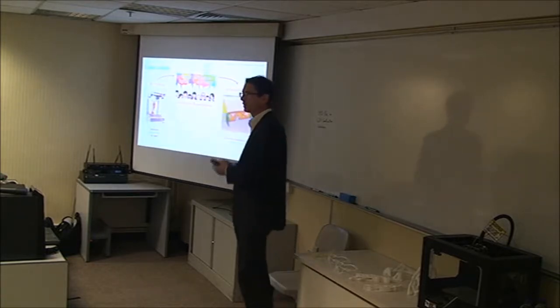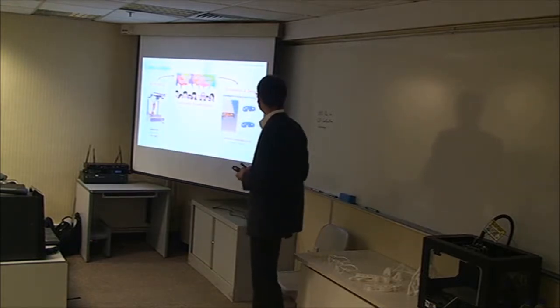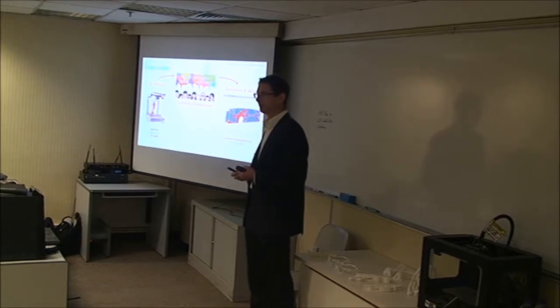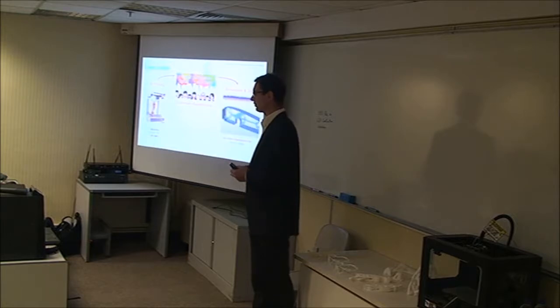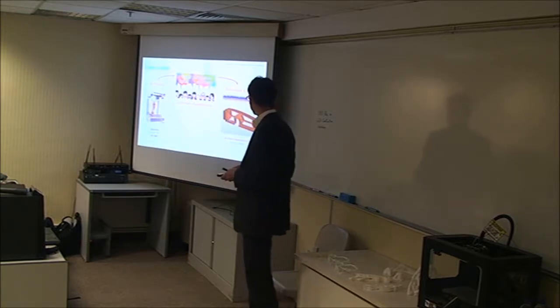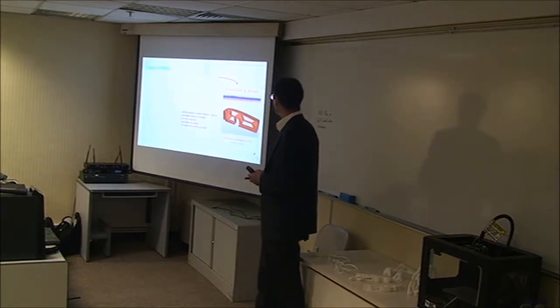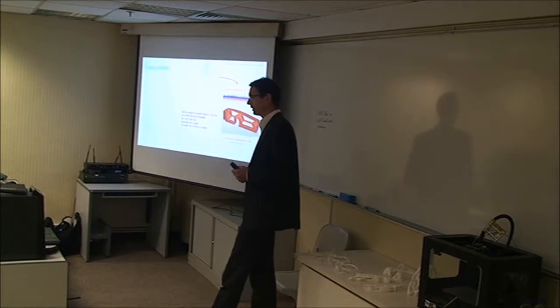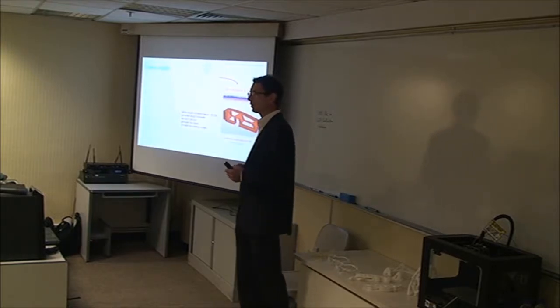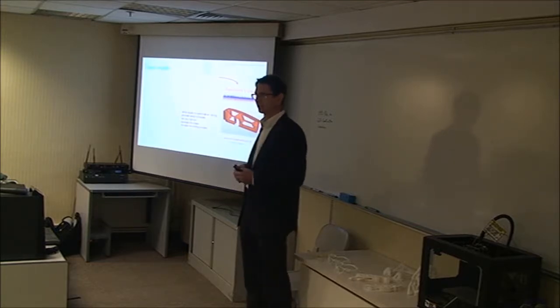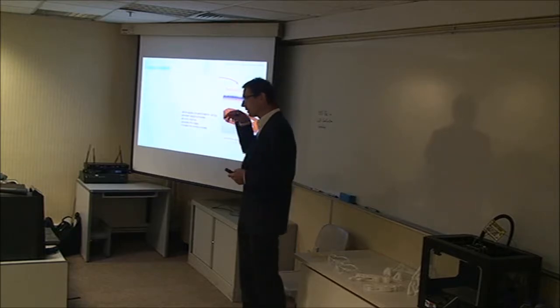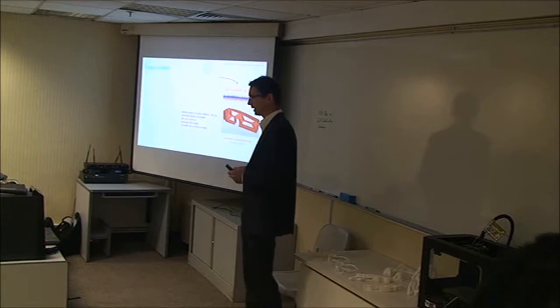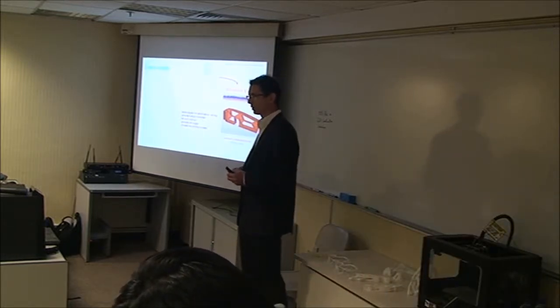So you look into the parts themselves. You look at how they perform. You find out the stresses, the load cycles they can stand for durability, for example, and that's where simulation is used. But therefore you have to define the target first, and that is very important when you do simulation and optimization, that you define exactly what you want to achieve. So what mechanical behavior characteristic you want to achieve, because when you do optimization, you target your design directly down to that specific performance characteristic, and that has to cover later on what you want to have in reality.